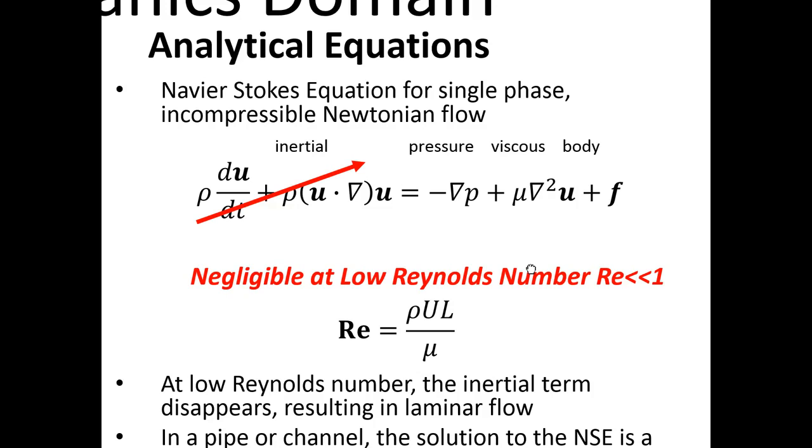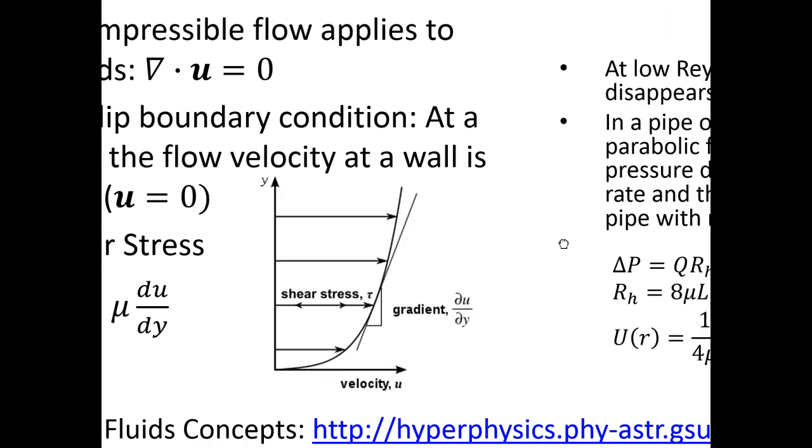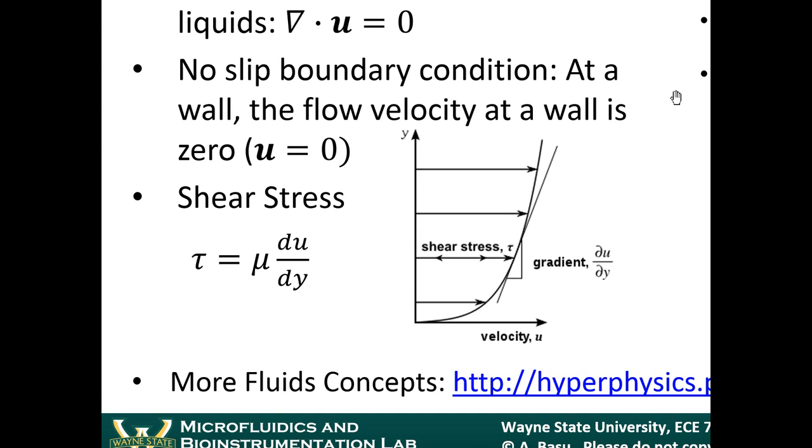Okay, the reason why I've included just this equation is because with microfluidics, this is generally what we are concerned with. There are more complex equations for compressible flow, and also if you have non-Newtonian flow, then also the equations change. By the way, Newtonian liquids. All right, you may have heard this term Newtonian versus non-Newtonian liquids. In a Newtonian liquid, the viscosity of the liquid remains fixed. Okay. In non-Newtonian liquids, the viscosity of the liquid can actually change depending on how much shear stress that you put on it. Okay. So going back to this mu would be a constant in a Newtonian liquid.